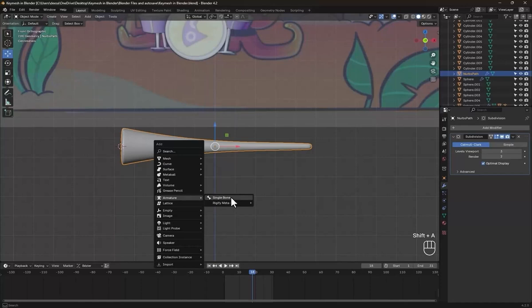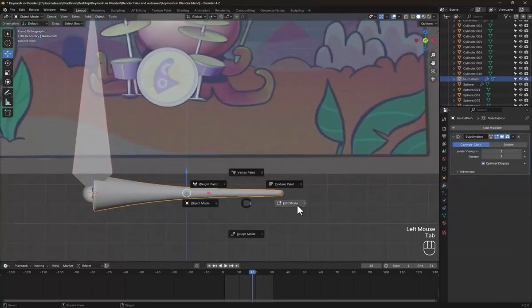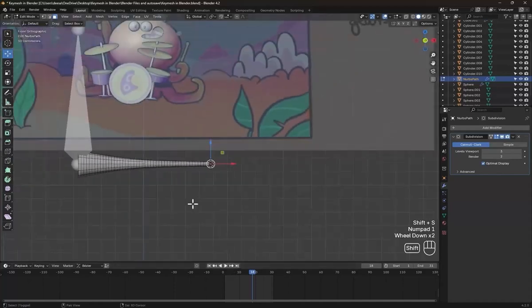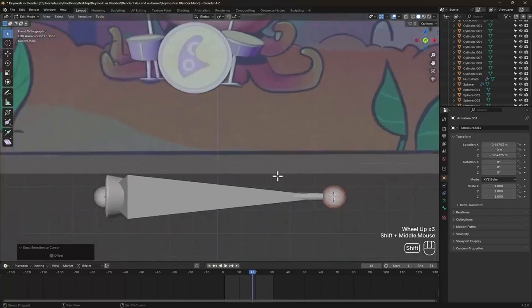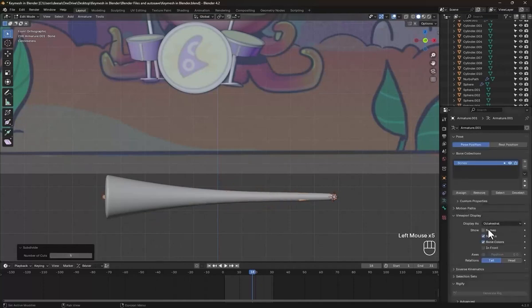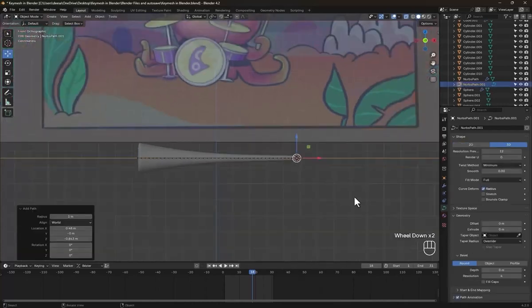Now add a single bone to match the size of the tentacle. I will move the origin to the front of the tentacle. And snap the bone head to it to exactly match the mesh size. And subdivide it to a good amount, 40 for example, and make the bones always in front. Now add another path curve to also match the mesh.